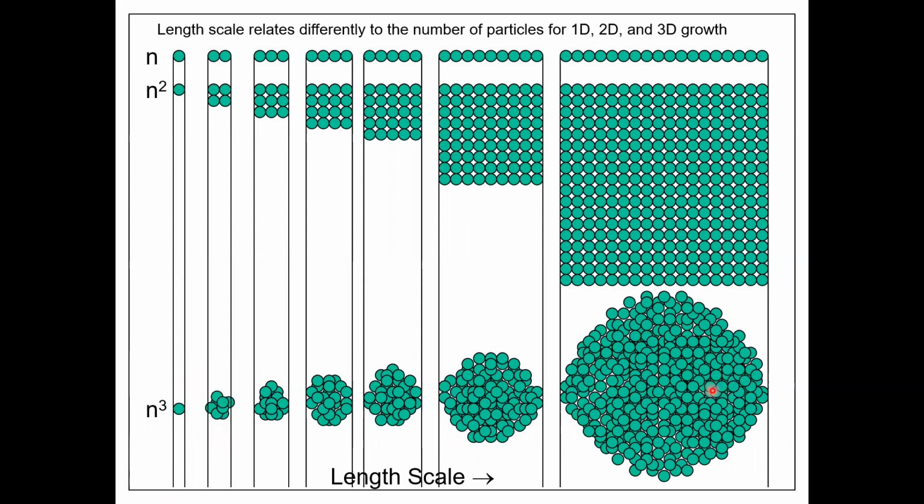So if I make a millimeter size piece of copper, as opposed to 5 nanometer copper, most of the copper atoms in that 5 nanometer material will reside on the surface and control the property, as opposed to millions of atoms residing in the bulk with only a handful residing on the surface. So there is no reason to expect that these two pieces of copper will behave the same way. That's a very, very important concept for material scientists.